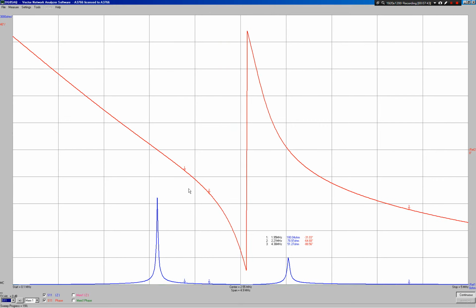There, now they are completely together. So the primary is now inside the secondary. The coupling coefficient will be quite high, more than 0.5, probably a little bit more. And you see the splitting of the upper and the lower frequencies is very well developed. We've got that phase change from the overall wire length. That started off down at 2.21, it's now moved up higher, to 2.6. Put that now back down at 2.21.